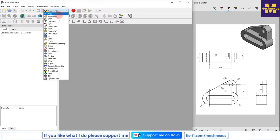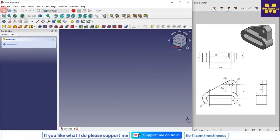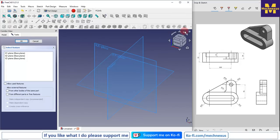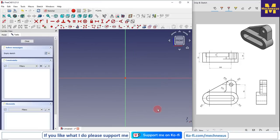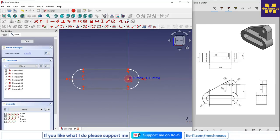So first I will switch to the Part Design workbench, and then I create a new file. I create a body and then create a sketch, and here I will use this XZ plane. And now we will create our sketch. So first I will select the slot tool, which you can find here, and I will create a slot, then again one more slot,